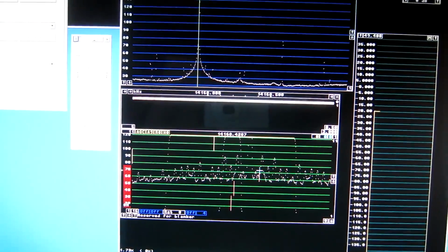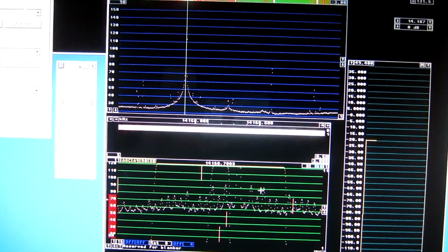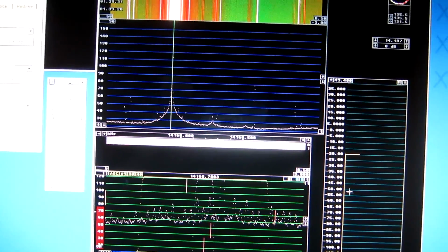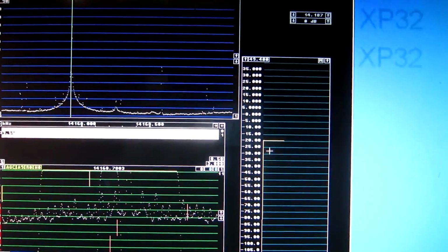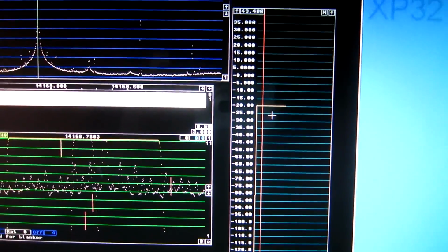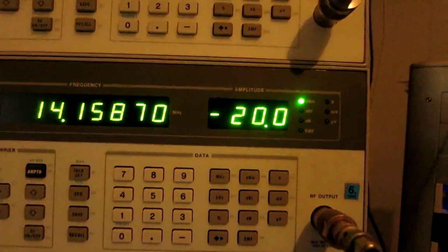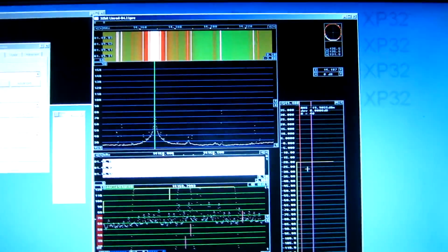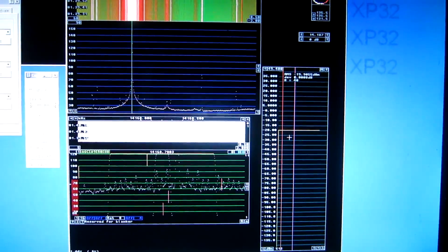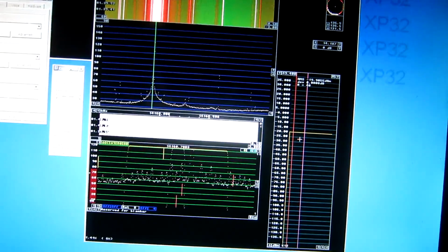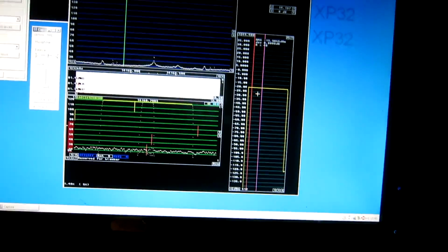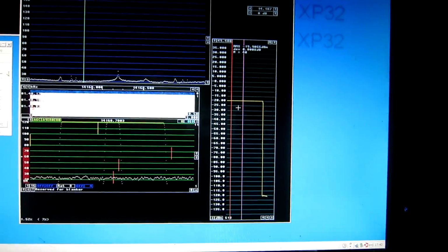Anyway, I go here and I set the gain. Seems I already did that. It shows now 19.9, while the true value is minus 20. That is accurate enough, so I switch off the signal generator to look at the noise floor.